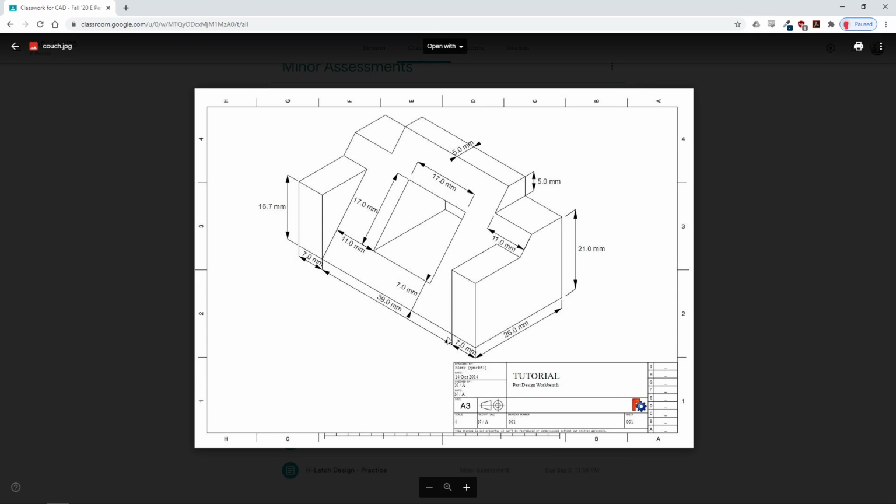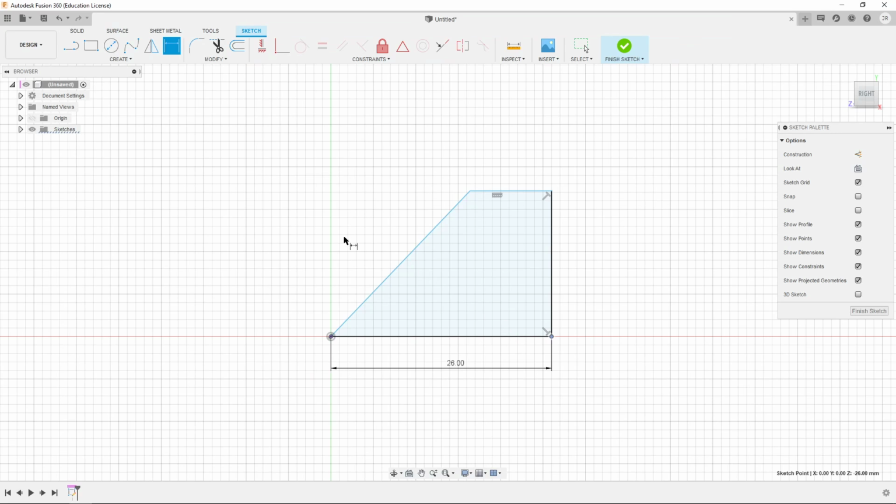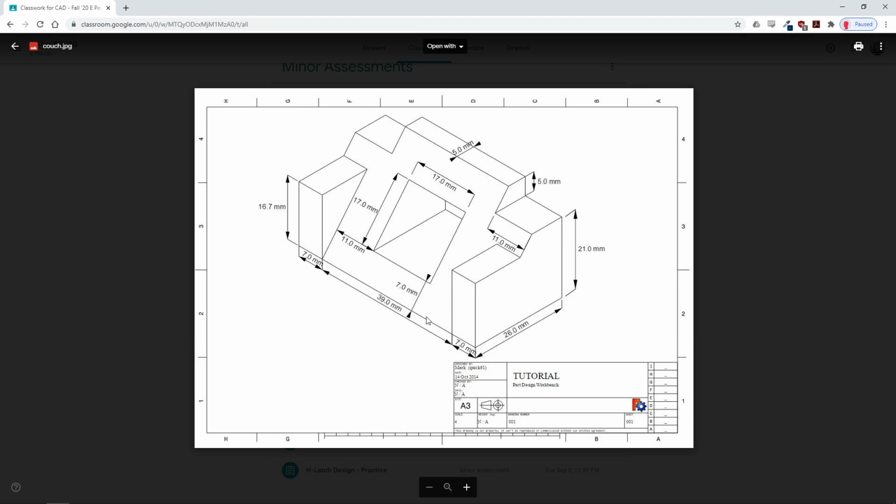Another dimension we might have, so I'll point out, we could dimension this one, but I don't know the length from my drawing. This angled line, its length is not apparent. It's the slope of this wall, but I don't know how tall it is. So we don't necessarily always have all dimensions in our drafts, but we can probably calculate it, or if we do it correctly, if we put other constraints, it may not even be necessary to dimension it.